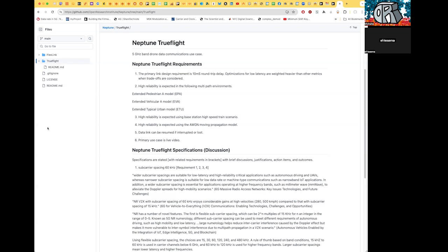Or you have regular heartbeats, either hardware or software related. If you lose the software one, you can tell which link is lost. The physical link hardware is still working, the software is not, and you can restart it more easily. If you lose both the software and the hardware heartbeat, you know you're completely blocked and you're going to have to command things to restart. So there's lots of choices here.